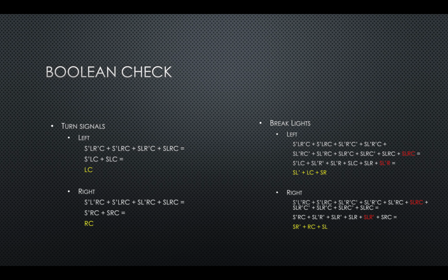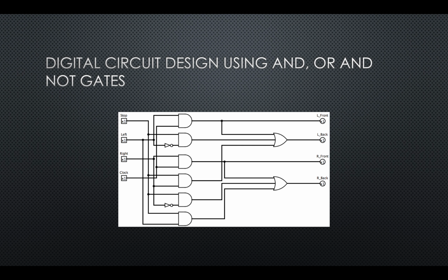As we apply the laws and theorems of the Boolean algebra to verify our K-map solutions, we come up with the reduced equations. We can now implement them into circuits. As we can see here, now that I have my simplified Boolean equations, I can now implement them using the AND, OR, NOT gates. I do this first because I am familiar with these gates, and it allows me to get a good idea of how the circuit runs before implementing it with a ROM or a lookup table circuit. It is also fairly easy to read it this way.